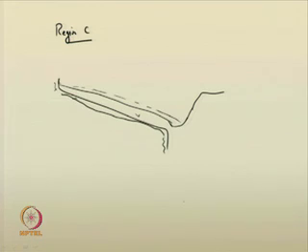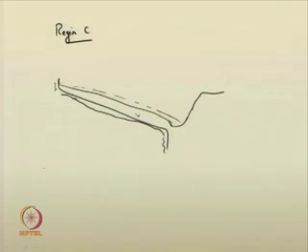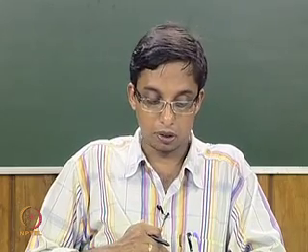Due to the supercritical conditions, it is considered as a region defined as region C. Region D is similar, but instead of a hydraulic jump, it will be purely merging with the water profile existing in the downstream. So, without hydraulic jump, that is how region D is also defined. According to our requirements, we are not interested to cover much deeper in these portions, and moreover this module has taken more lectures also. We try to minimize the portion here.